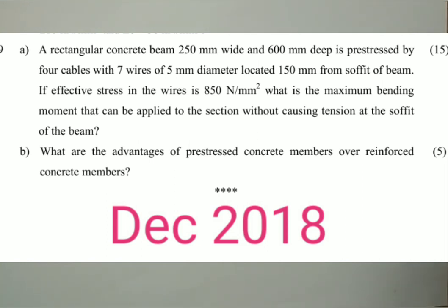Then, since there is no cracking in a pre-stressed concrete beam, its behavior can be explained in a more accurate manner. Then, in pre-stressed concrete, the sections are much smaller than those in RCC, as the dead load moments are neutralized by the pre-stressing moments and shear stresses are reduced. Then, pre-stressed concrete has the ability to resist impact and shock loadings. Therefore, it can be used for the construction of road and railway bridges. Also, it has high fatigue resistance and live load carrying capacity.